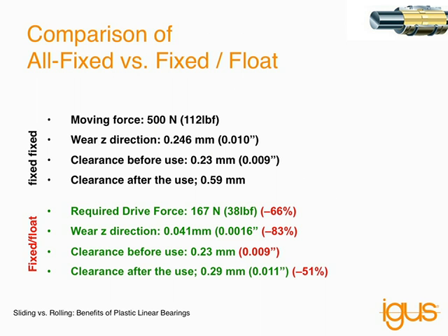Now this is the really cool part. I really like to show this benefit to engineers I visit who are skeptical about the use of floating bearings. A lot of people think, and it's kind of common sense, that by introducing a set of bearings that has enhanced clearance you're going to increase the clearance in the whole system, when in fact it's not really like that. That fixed bearing side will define the precision of the system.